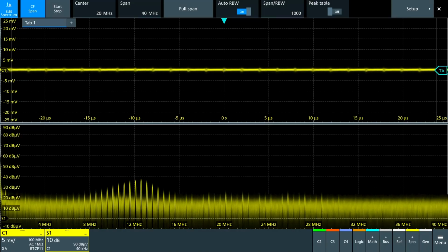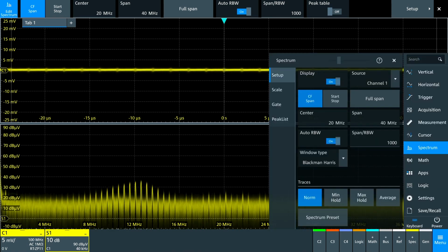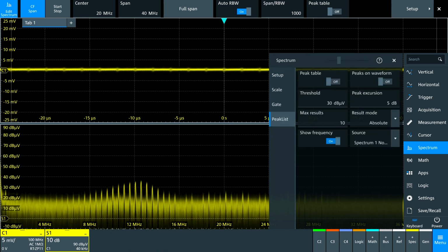The controls on the spectrum view are very similar to those on a normal spectrum analyzer instrument, they are broadly decoupled from the time domain view. The resolution bandwidth can be set to very low values, and the display still updates fast like a real-time spectral analyzer or a software-defined radio. A major benefit, though, is that it works down to DC.